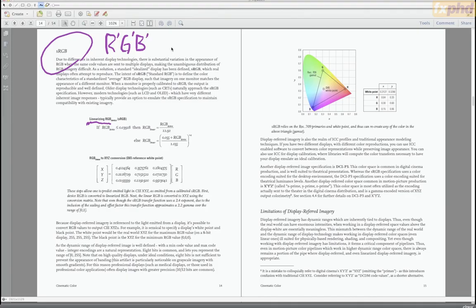I put primes on the RGB. And, you know, we all know that it runs from 0, which is reference black, to 255, or if you like, 255, 255, 255, which is white. But in the middle, it's gamma corrected. So it's subject to a gamma curve on the way out from video signal code to linear light tristimulus. And I've been saying all along in this course that the power function is 2.2.